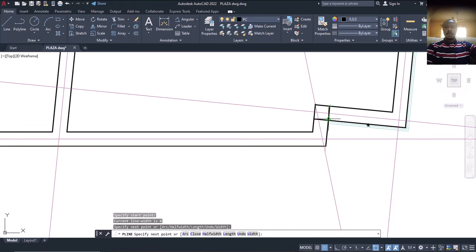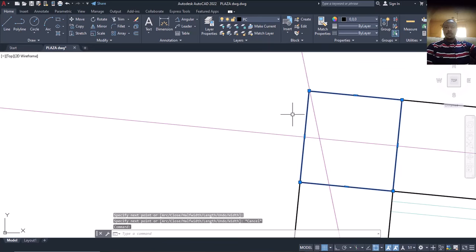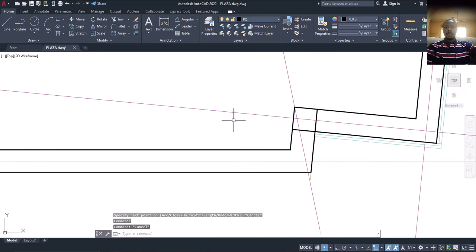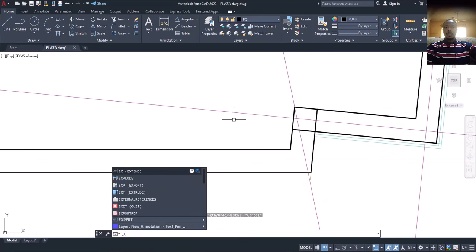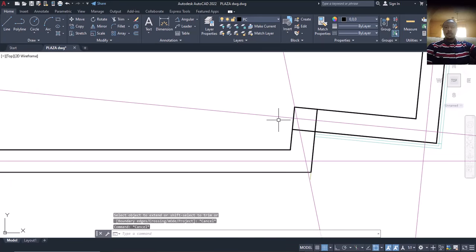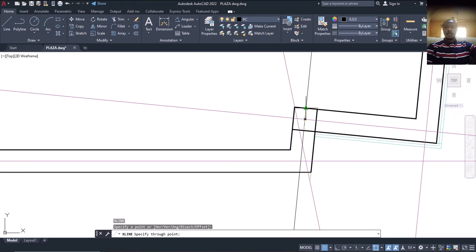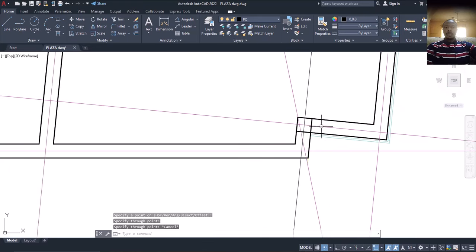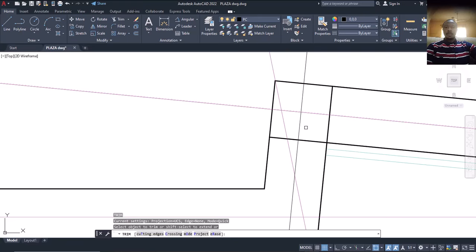All right. Click on this one and this one and also this one and this one. Okay. I hope it's connected. Okay, they are connected. All right. I'll now pick my XL again. Enter. Sorry. XL, enter, come here, this is center, and also come here. Can you see? Fix it there. That's fine. So I'll come here now, TR, enter. Wait, let me delete that one first. Okay, then TR, enter, and trim these ones off.